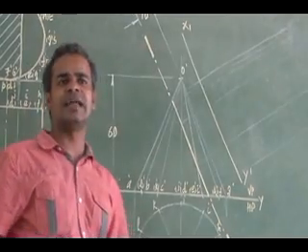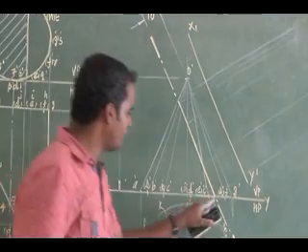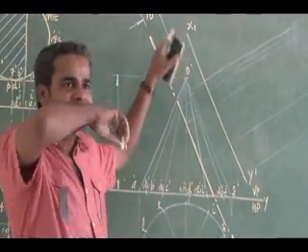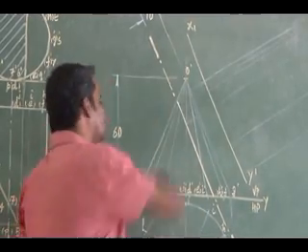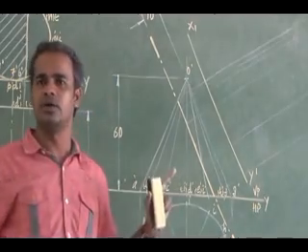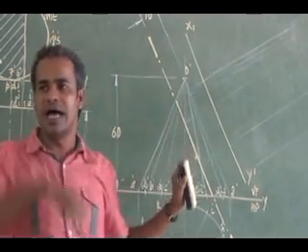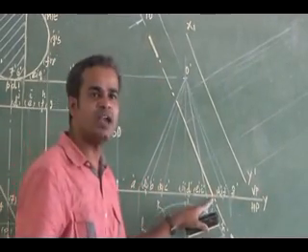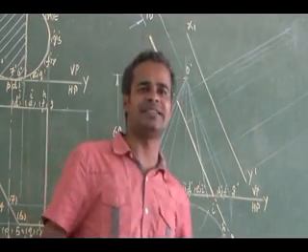Then giving the cutting points, notating the cutting points, listen, from here you can start, right? Or from here you can start. Or either this cutting plane can be represented parallel to this AO generator. It's up to you. So I have made it parallel to GO. Right? So I am giving the cutting point notation. Listen, starting from the bottom I am giving, searching for the visible cutting edges.